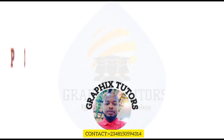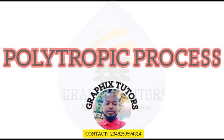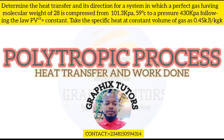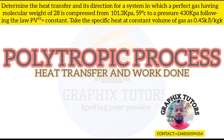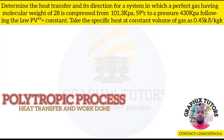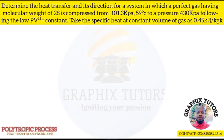If you look at the front of your screen, you will see a question, and the question says, determine the heat transfer and its direction from a system in which a perfect gas having a molecular weight of 28 is compressed from 101.3 kilopascal at 50 degrees Celsius to a pressure of 430 kilopascal following the law PV to the power of 1.3 equals constant. Take the specific heat at constant volume of the gas as 0.45 kilojoule per kilogram Kelvin. Now, what you see here, kilojoule per kilogram Kelvin, is telling you that any temperature you have that is not in Kelvin, convert it to Kelvin.